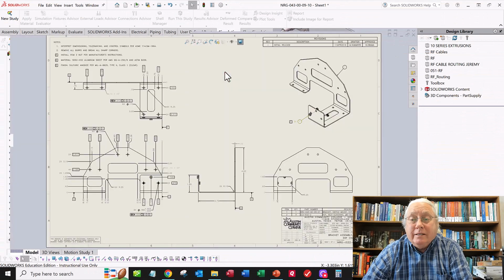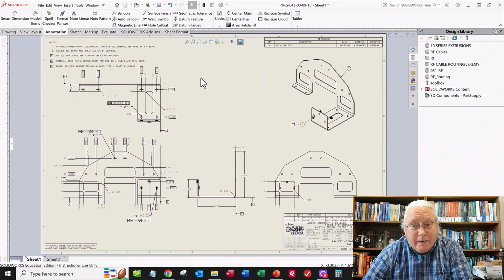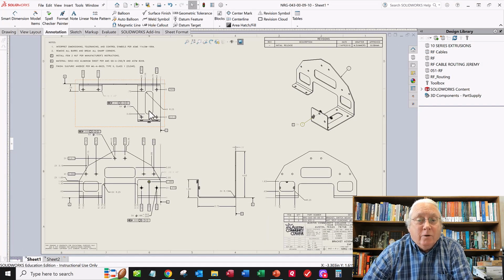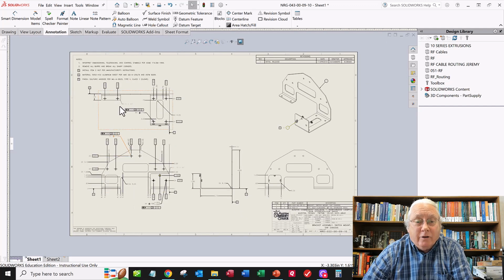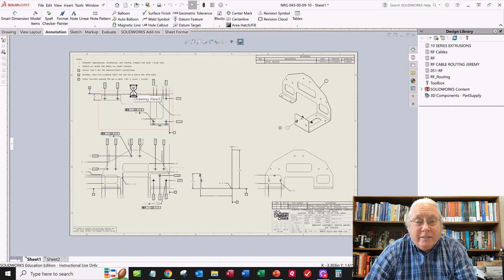And I've got one more picture here. In addition to doing the mechanical design, we also do drawings. We'll learn about geometric dimensioning and tolerancing, how to do drawing views, how to specify the manufacturing processes and the dimensions and the tolerances, all using standards, in our case ASME Y14.5, and learn about that.